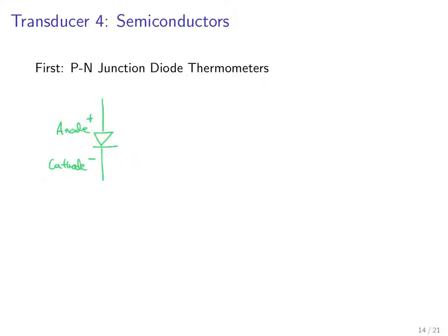And these were the first semiconductor devices. And they're made by bringing two different types of doped semiconductor material together, sort of blowing up the schematic here. You bring together a p-type semiconductor and an n-type semiconductor. And the p-type semiconductor is doped with impurities that steal electrons from the silicon's valence band.